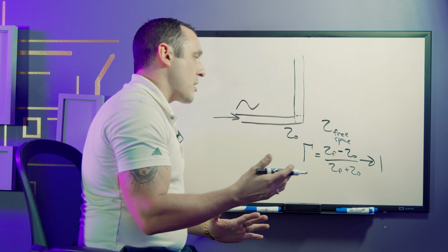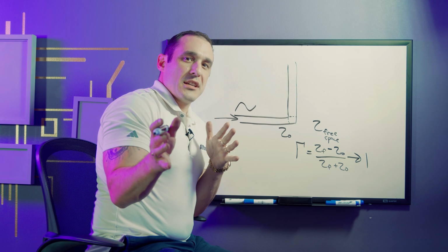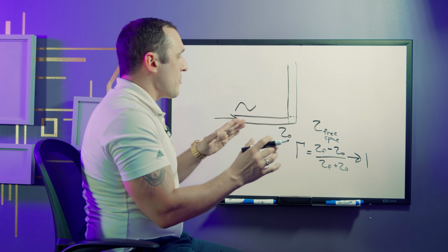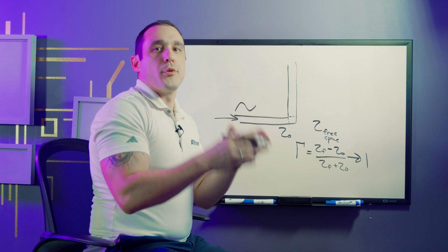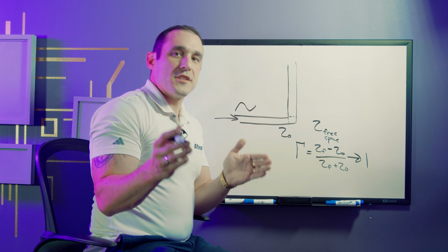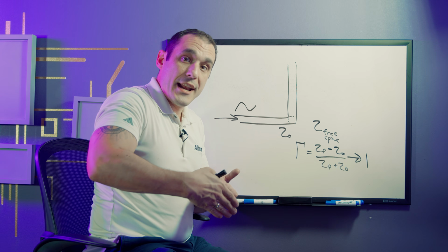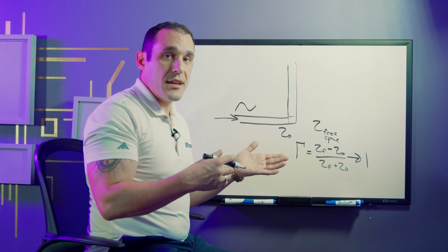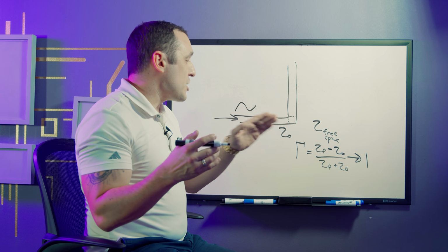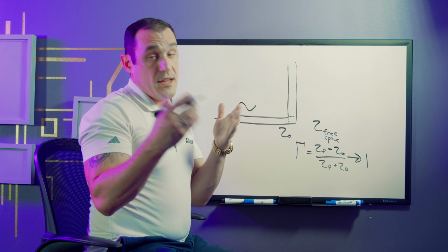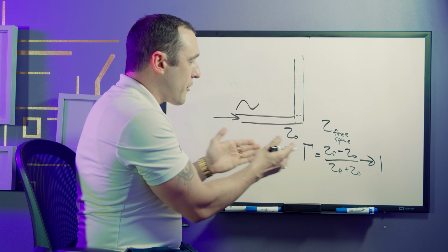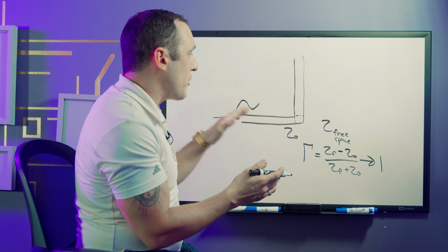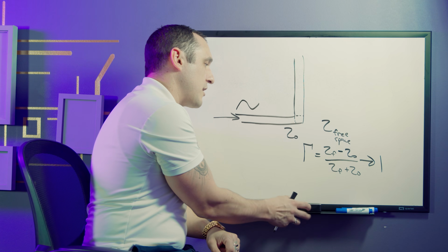Now, this is what's really interesting about this myth: everybody says this will happen in 90-degree traces, but they never bring up vias. And of course, vias are also a form of a right angle bend for routing in PCBs, and nobody ever brings up this huge reflection in vias, even though it is also a right angle turn. So why do people bring up this very basic misunderstanding about signal propagation along these right angle traces?